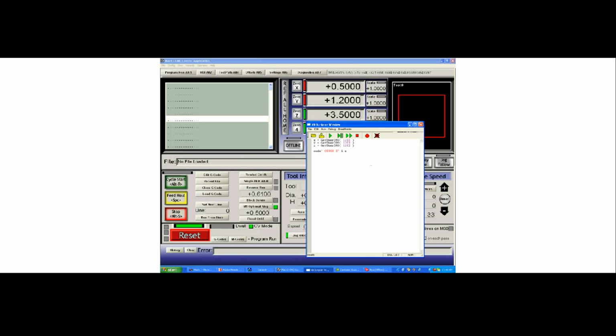Now, what can be important in some programs is that you delay further statements until a previous statement is done. It's not always necessary, and let's try it without it first. We'll do a code G53. We're already in G0 because G0 is a modal command, and we put a G0 on the previous line.